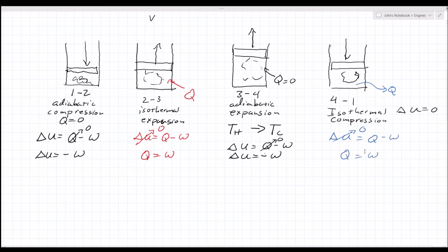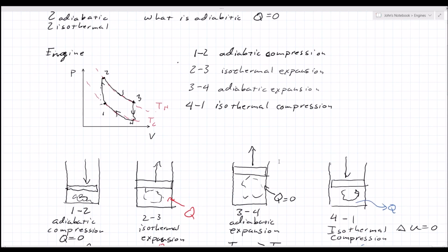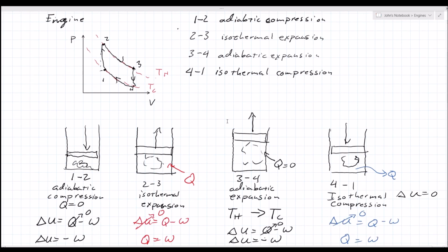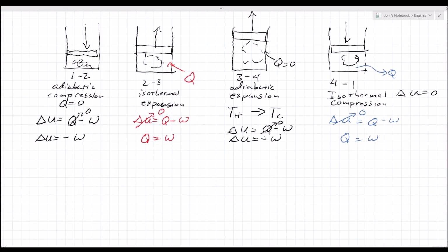So this is a Carnot engine. The Carnot engine, again, is the simplest type of engine. It's the most ideal engine you can make, so it has the highest efficiency you can get between two temperatures. Remember, according to the second law, to get work out of a system, you have to have heat or energy flowing from high to low. So if you have your high system and your low system, you can use the Carnot engine to determine the highest efficiency you can possibly get. We'll be doing some examples of that later.